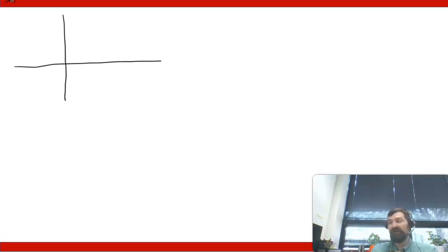Now there's a second thing that we can define, and it's maybe worth redrawing our phasor diagram for an RLC circuit generically. And that second thing that we can define is what's called the phase angle for the circuit. Let's say that this first arrow could represent our current at a given time. So this is I naught.